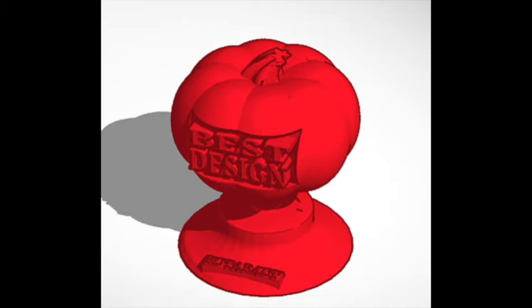There were definitely a lot of supports that I needed to cut off and get those details out of. The issue, however, wasn't with the overall design. It was with this little part in the middle here that says best design. That was a problem because it was too detailed. And so the supports actually ended up getting stuck in there. And when I was trying to cut them off, they would clip off some of the parts of the letters, and some of the filament would get stuck in between the two words. And so that ended up being a little bit of a mess. But overall, it turned out to be an okay design.